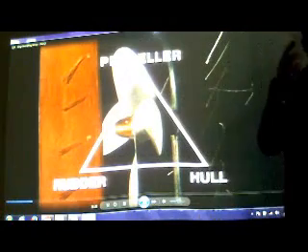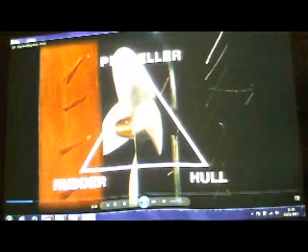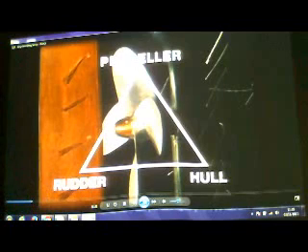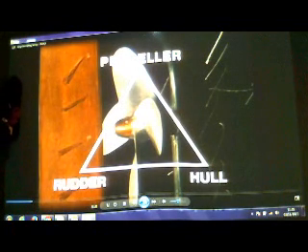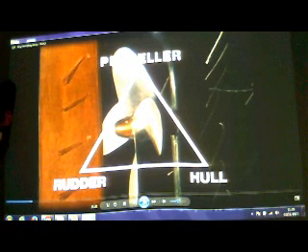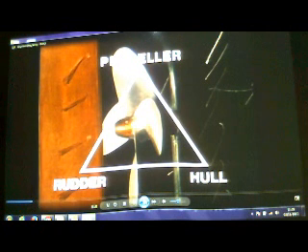It just mentioned two things, transverse forces, so you must be wondering because we did not cover that in slide. So your vessel is designed to go like this, generally 90% of the time, but when your vessel is actually maneuvering, coming alongside to another vessel, your vessel needs to do this as well. Move athwartship. Well, these transverse forces you need to be bearing in your mind and be then deciding what you need to do to use these transverse forces to your advantage when you are doing this close quarter maneuvering, when you're going alongside, going off, bearing that in mind.